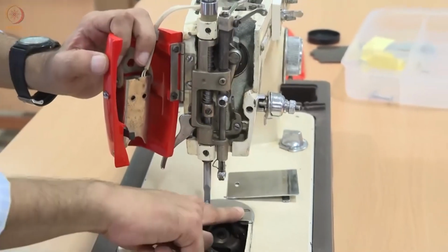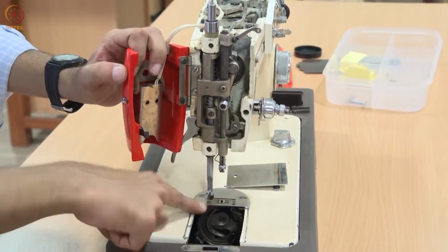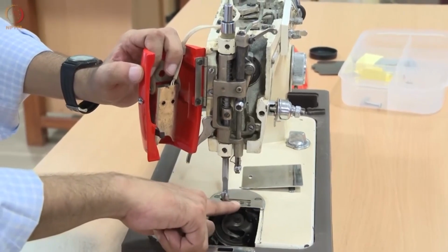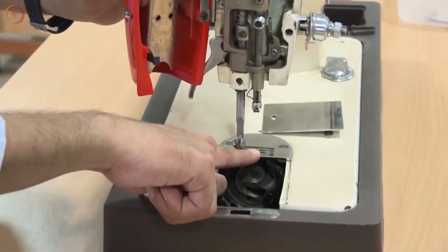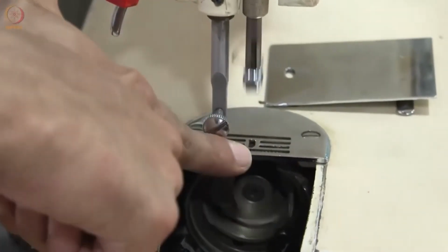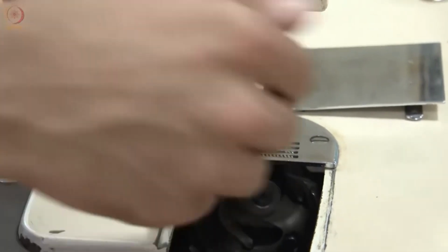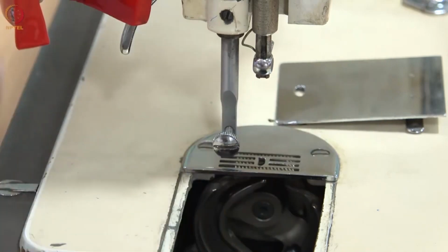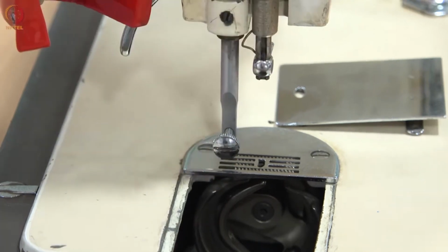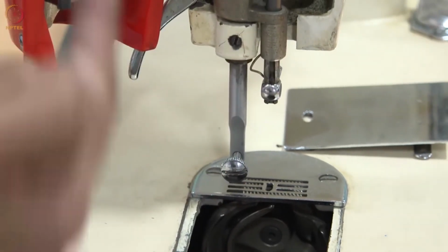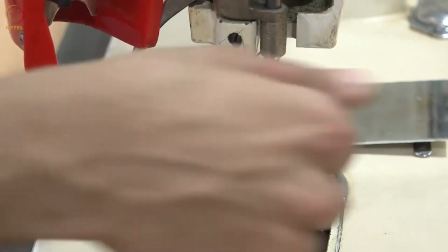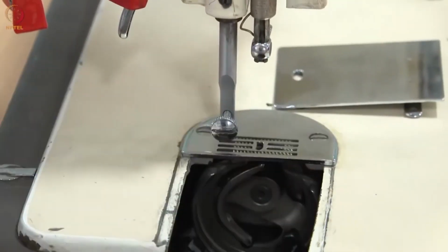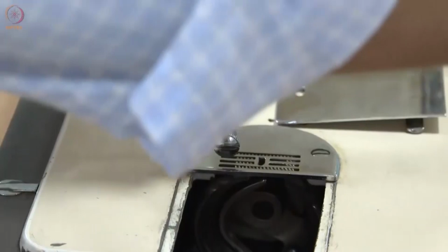The reason why we have this mechanism is, when it is stitching, you need to advance the cloth at a specified rate, right? This is what we call a pitch, the distance between two consecutive insertion points of the needle. In other words, the nodes. If you look at a sine wave, it's the zero points, the nodes of the sine wave. That advancing is done automatically because you don't have to feed it in. The cloth is pulled by the machine inside.